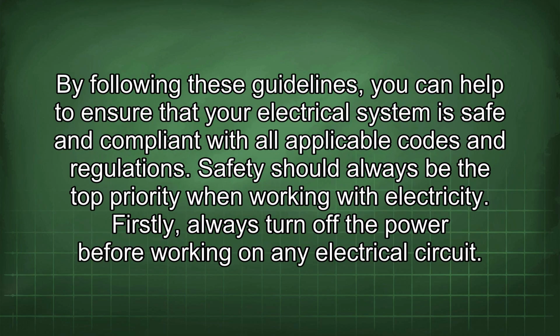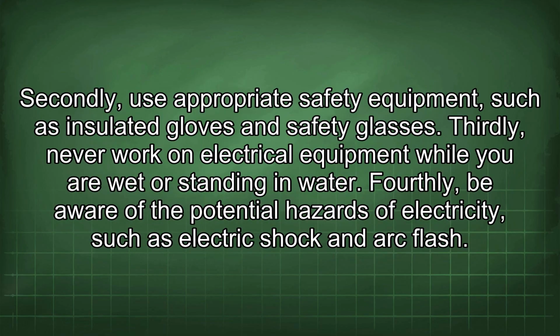By following these guidelines, you can help to ensure that your electrical system is safe and compliant with all applicable codes and regulations. Safety should always be the top priority when working with electricity. Firstly, always turn off the power before working on any electrical circuit. Secondly, use appropriate safety equipment such as insulated gloves and safety glasses. Thirdly, never work on electrical equipment while you are wet or standing in water.